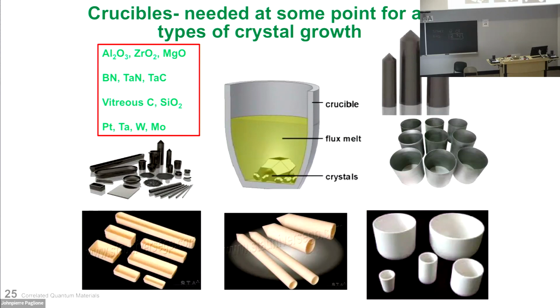And so there's a lot of different places you can nucleate manganese bismuth crystals because of the gradient. And if you have a lot of little teeny nucleation, little tiny crystals of manganese bismuth, that limits how large your biggest crystal can be.